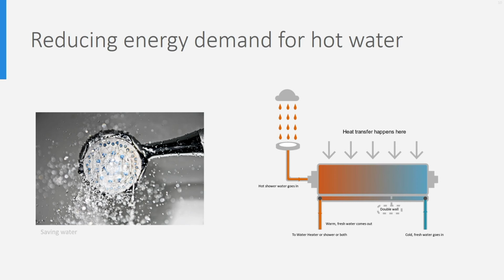If we cannot reduce the temperature of the warm tap water, we can instead increase the temperature of the cold water. This will also reduce the temperature difference, and this is possible using a heat recovery system. Do you remember the heat recovery system for the ventilation part?